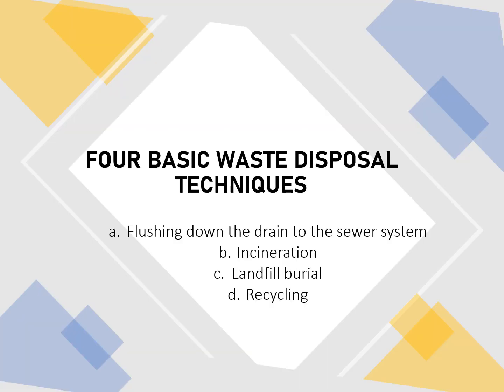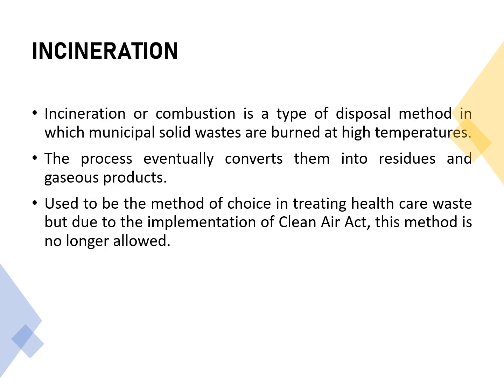So we are already in the last part of our discussion, wherein we are going to discuss the four basic waste disposal techniques, such as flushing down the drain to the sewer system, incineration, landfill burial, and recycling. For flushing down the drain to the sewer system, this is only applicable for non-hazardous chemical waste. So we start with incineration.